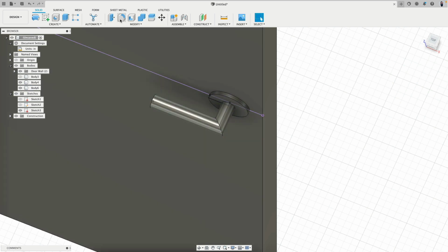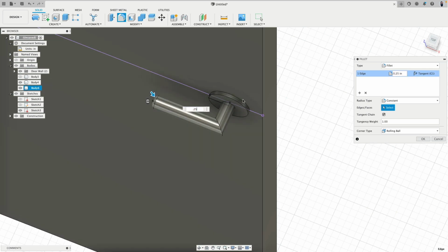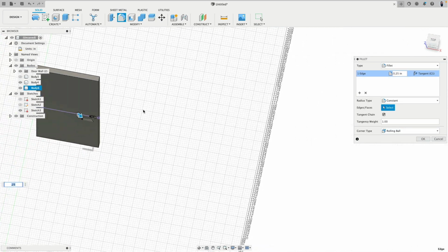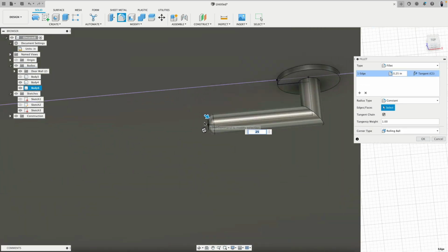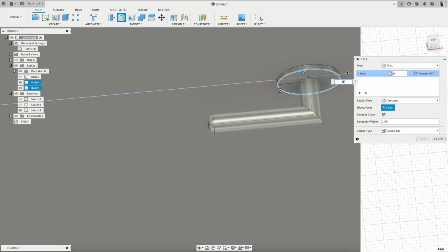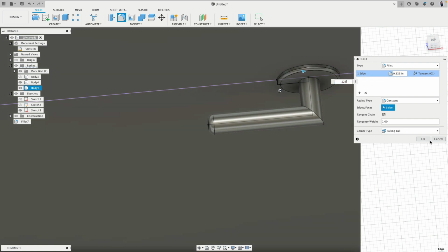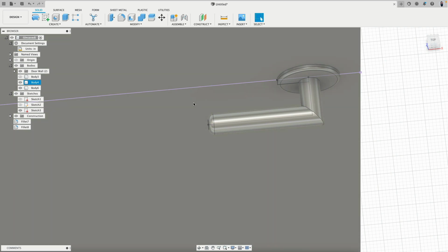This edge is really hard. We could go to fillet command and say 0.25 to round this. There we are. And right click and say repeat fillet, or call this command again, and then here 0.125. Look at that, no? So we nicely rounded these sharp corners.